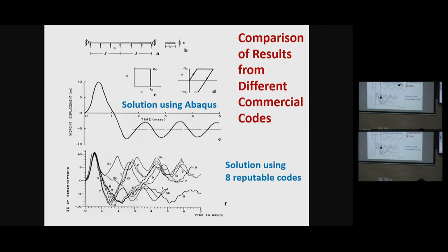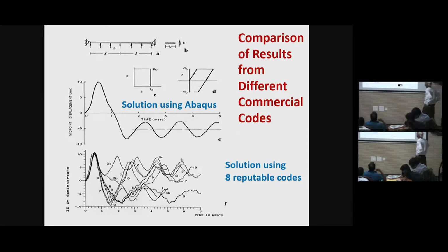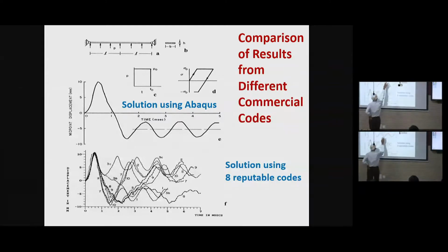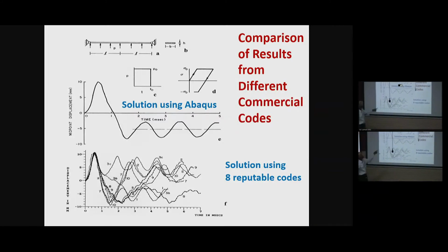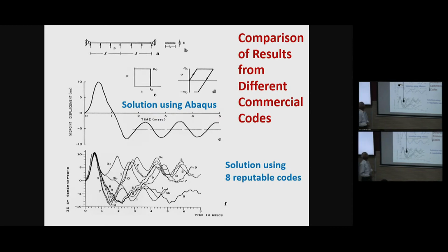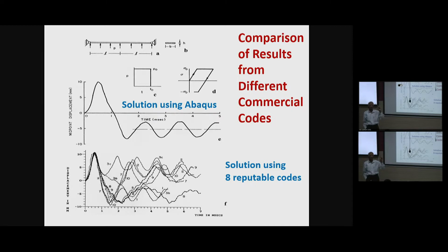So, if you take an elastic plastic plate, the stress strain law is shown here. It's an elastic, perfectly plastic material. And you apply a pressure pulse, uniformly distributed. In this case, the load is going up, but it doesn't matter whether it's coming down or going up. You apply pressure for T0. So the critical things are the magnitude of the pressure P0, the height, and the duration.